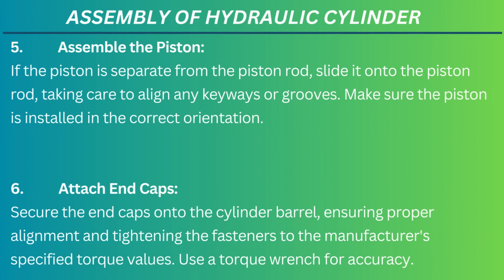6. Attach end caps. Secure the end caps onto the cylinder barrel, ensuring proper alignment and tightening the fasteners to the manufacturer's specified torque values. Use a torque wrench for accuracy.